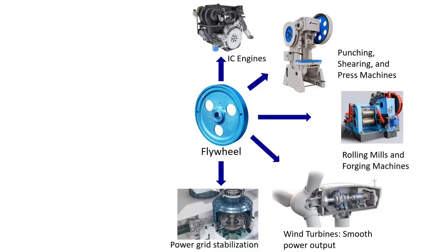So all these are huge rotating masses, and these rotating masses can absorb energy and supply energy, acting as a flywheel. And when there are interruptions, for example, if a transmission line is tripped off, there can be a sudden drop of power, and the energy demand will drop instantaneously, and that drop can be absorbed by these rotating discs.